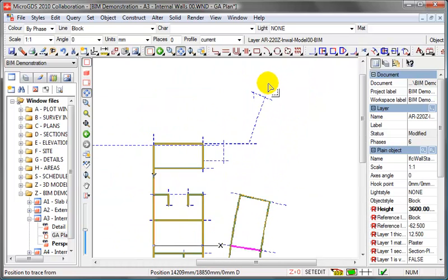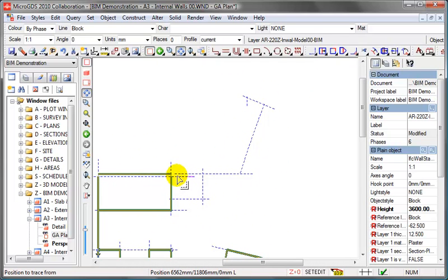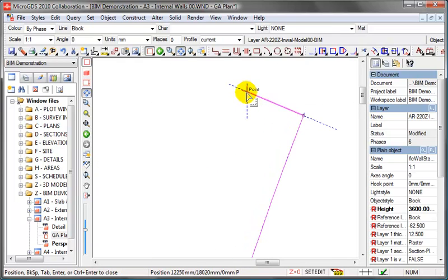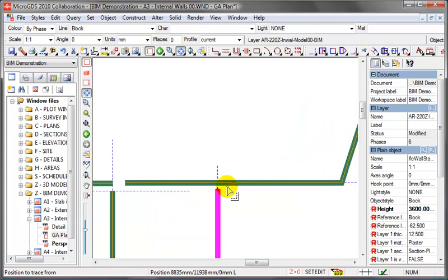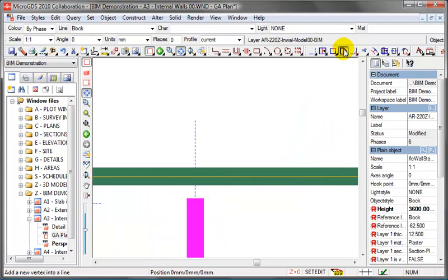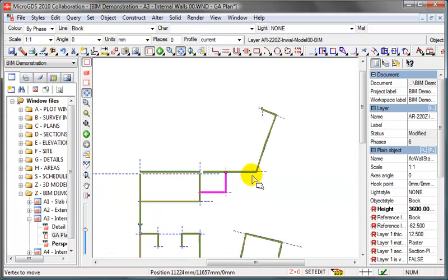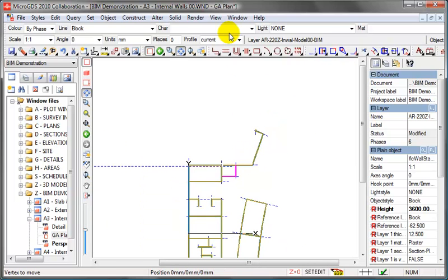And similarly, this final section here, where we have another curved wall, again we've faceted this, and then just a little stub there that we need to make sure goes in, and the lift shaft here in the corner. I've stopped short there so we can use our alter vertex move command to just make sure that the walls match through. That's all of the ground floor walls done.